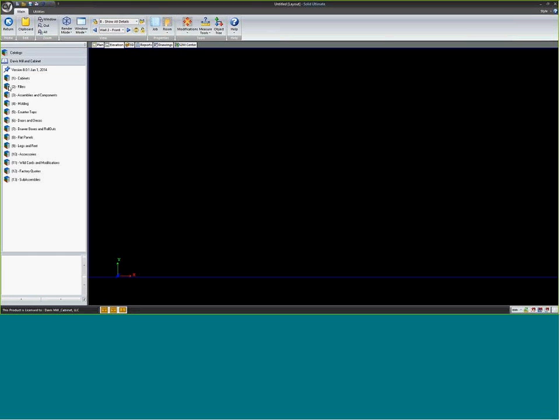Basics on the cabinets. Fillers, options that we've done in version 8 now. Most of you have seen this, but wood options or veneer. You want to use the veneer options only if you have veneer slab doors. Otherwise, use solid wood filler options. Within the fillers, the options will be the same whether you're in solid wood or under veneer. Solid wood for now.